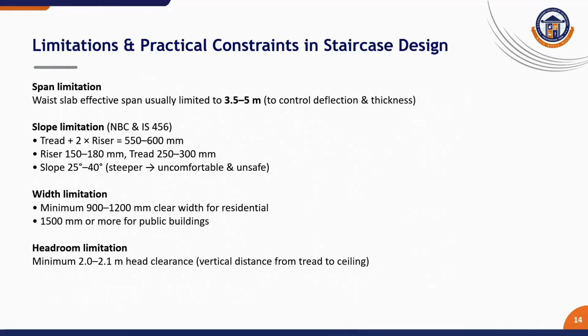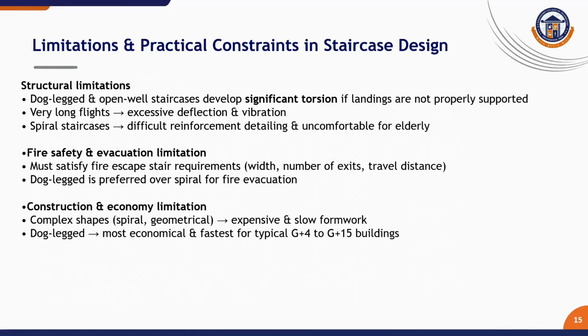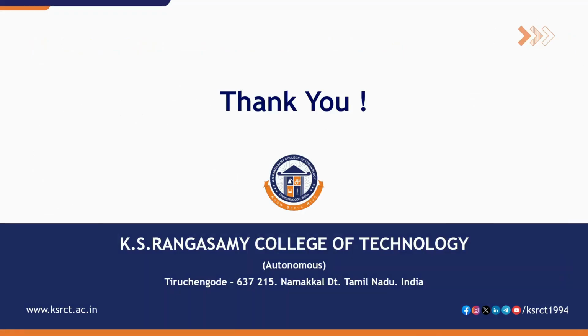Structural limitations: dog leg staircase may develop torsion if not properly supported. Fire safety: dog leg staircases are preferred for evacuation. Construction economy: dog leg is more economical for typical buildings. These are all the structural limitations, fire safety and construction economy considerations.